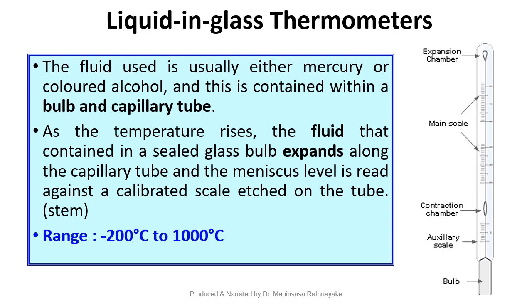Normally we use mercury or a similar heat conductive fluid with a bulb and a capillary tube. So you can see in the figure in the slide, there is a bulb and a capillary tube with the scale, and accordingly when we place the bulb at the unknown temperature, the fluid expands and it shows the temperature measurement because the expansion of the fluid is directly proportional to the temperature change.